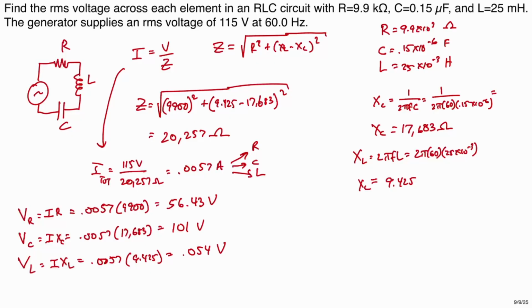But because we're calculating these RMS values and ignoring the time dependence of these circuits, we can't really just look at these and go, oh, it didn't add up to 115, I must have screwed up. No, that doesn't work that way, right? So again, we're hiding a lot of things in the black box of impedance and these reactances that make it hard to check. And so really, the check for a lot of these things is check your math, right?